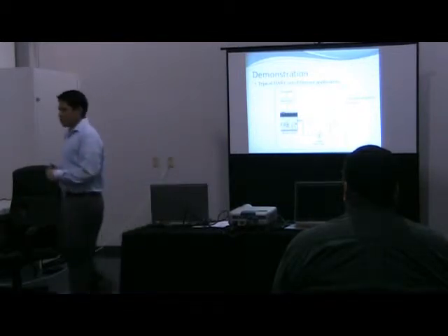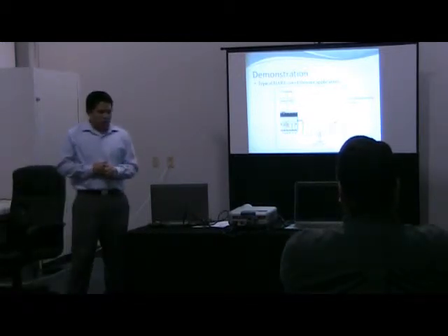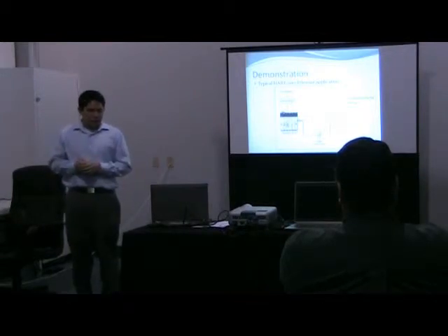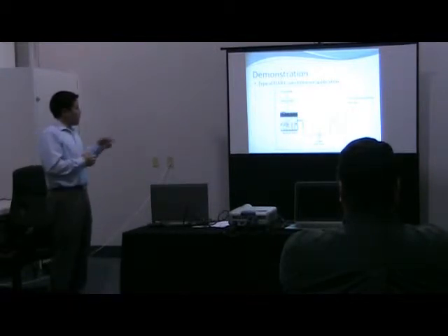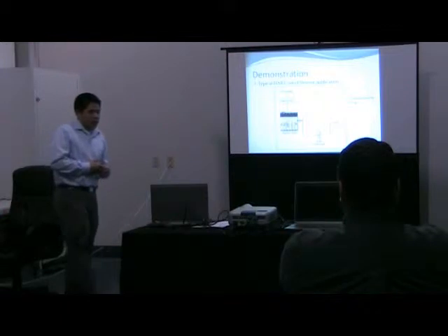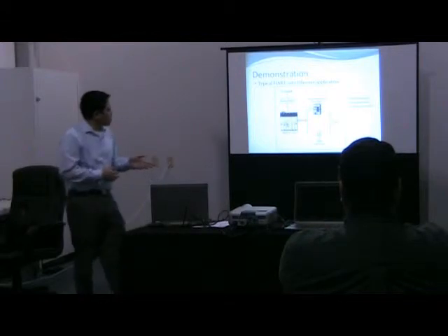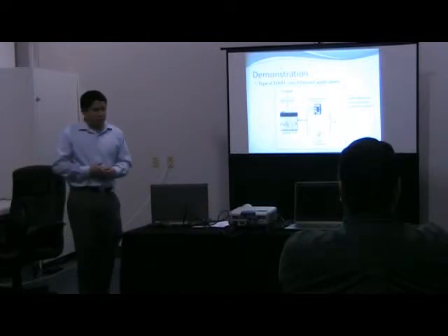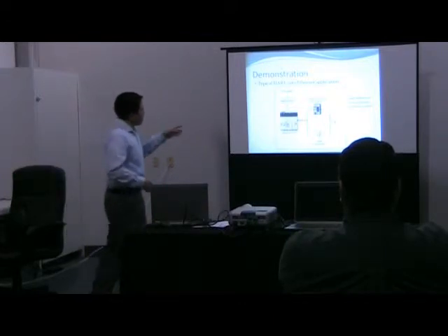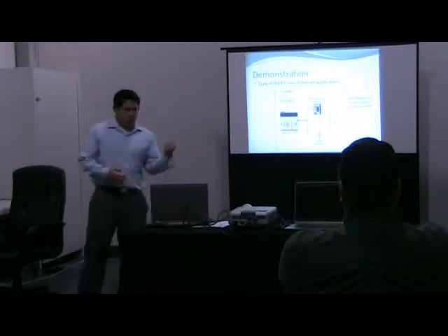So to introduce our demonstration today, we're first going to go over your typical HART over Ethernet application. This image shows your two-wire device, loop power, and your analog input card. To get it over Ethernet, we install a HART modem in series with the devices, such as the Spectrum field port that we have here for our demo. Like we were talking about, we were able to use the existing architecture by tying the HART modem into the existing Ethernet switch.